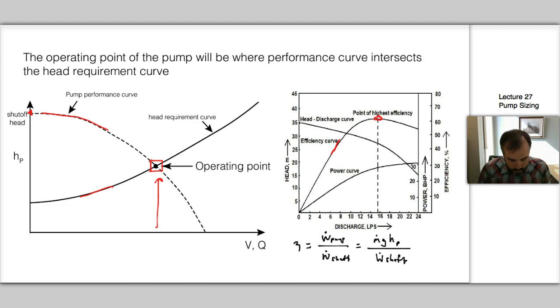Okay, so if you had a pump curve, and these are also published, the figure I showed before didn't show this, but a pump performance curve is often published with the efficiency curve. In fact, they'll be on the same plot like I show here, where they actually show the amount of power that the pump is putting in, the efficiency, and that head pump performance curve or head discharge curve.